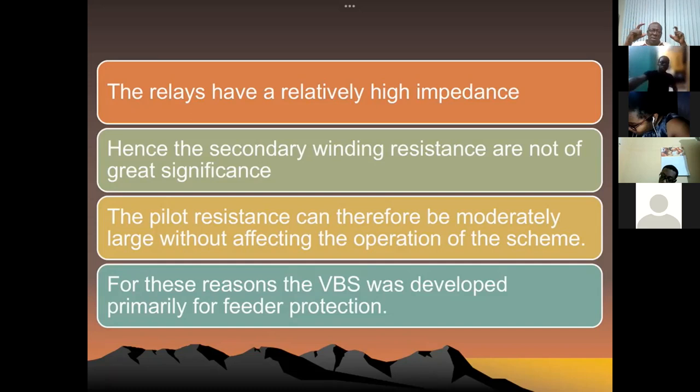All right. I remember one of the things we pointed out earlier in the module, that based on the impedance of the power circuit, when we referred all of that to the secondary, we saw that we could have a wide range of relays in terms of burden, because of what was happening with the excitation winding of your CTs.